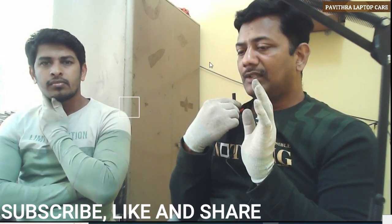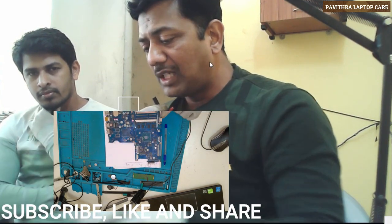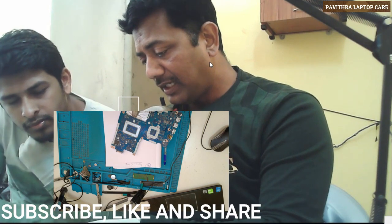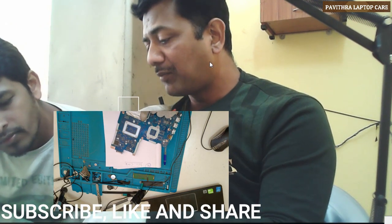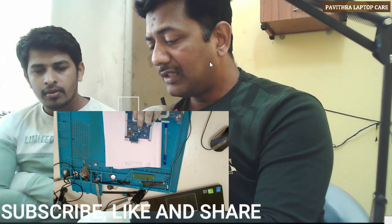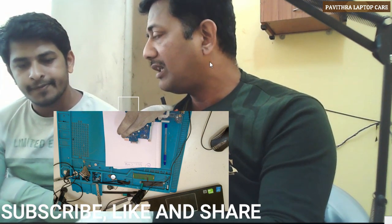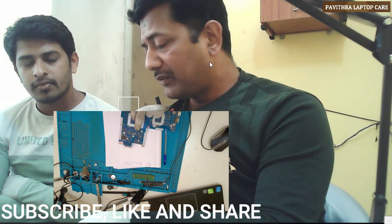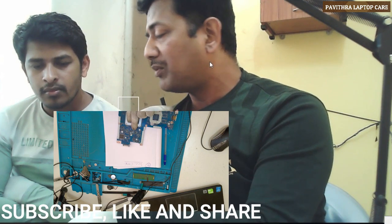Okay. So now I'm telling about this motherboard. It's LA-C811P. Okay. This is a 4th, 5th generation, means this is a 5th generation processor. For this processor, we have this particular CPU IC, RT8171C. For that, a dual MOSFET is also there. See, we came to know some components are missing.